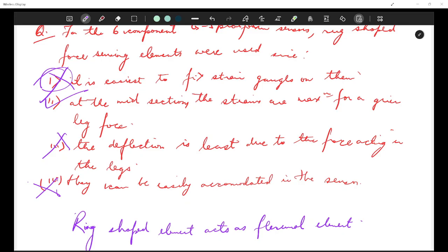This is correct. Why? Because the determinant of the H matrix is equal to 0, which implies the rank of H is less than 6. So when singular, the system loses stiffness in at least one direction, but not necessarily in all the directions. If it was singular in all 6 directions, rank would be 0. No force could be transmitted, legs would be contributing nothing. So that would mean the platform is completely disconnected mechanically.